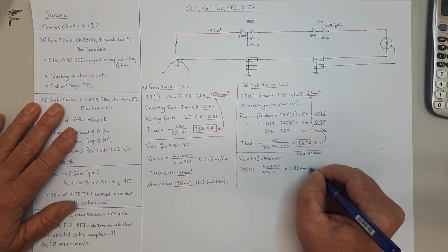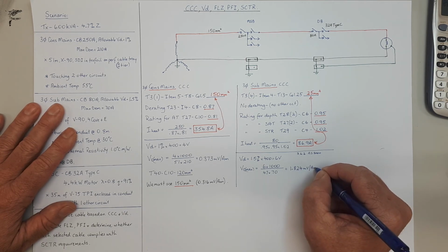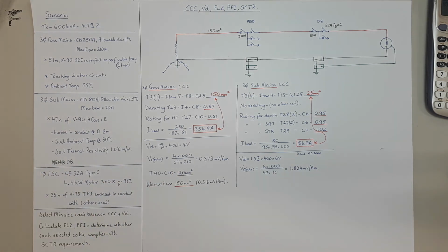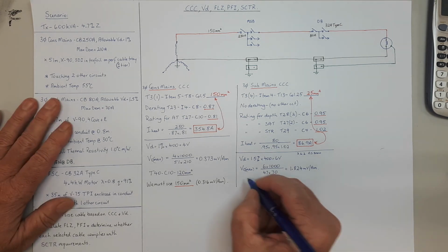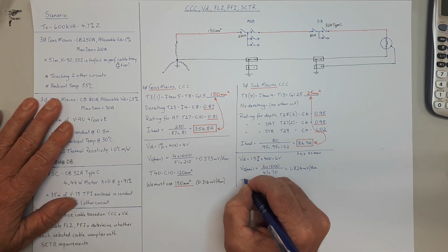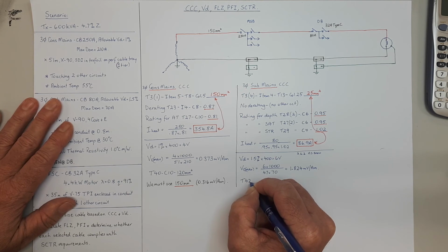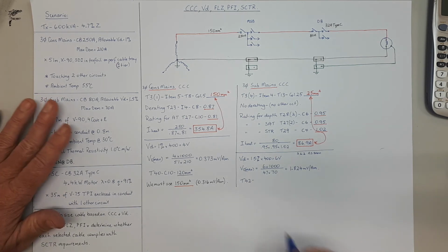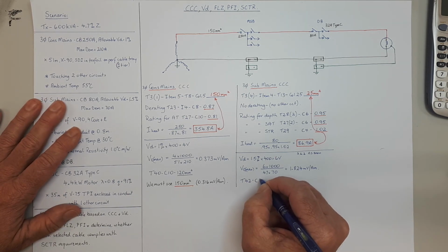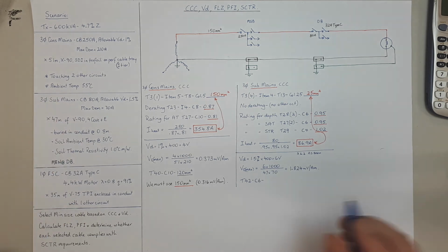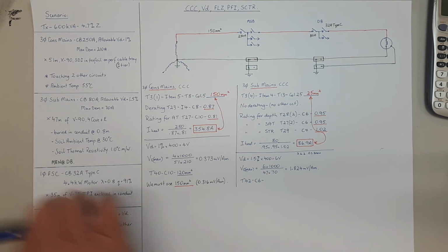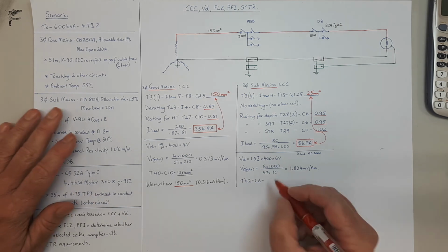millivolts per ampere meter. Now, of course, this is multi-core, so some of you probably know off the top of your head, multi-core straight to table 42. And it's 75-degree cable, so you go straight to column 6. All right, and then we run our finger down that, and you'll find that, as it turns out, 25 mil is the right size cable.